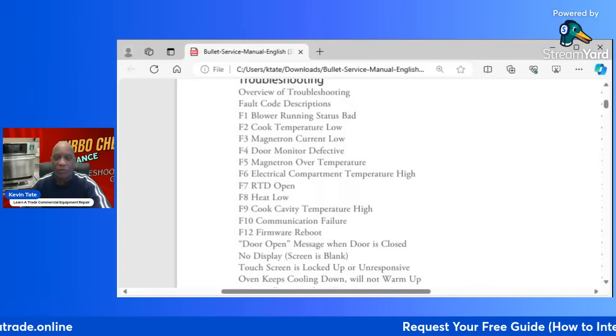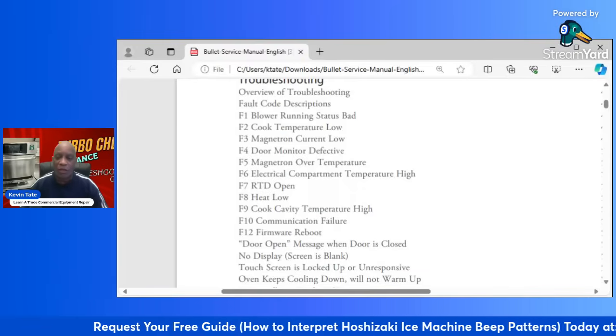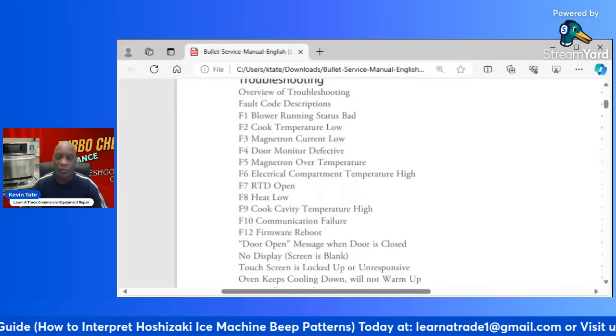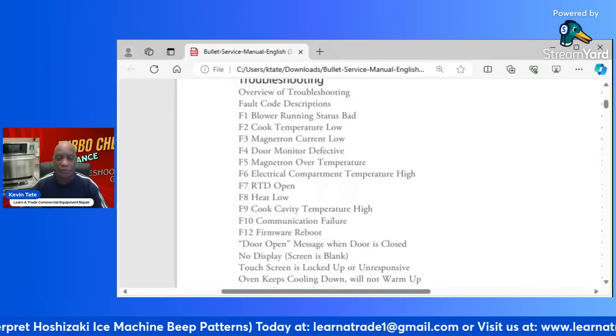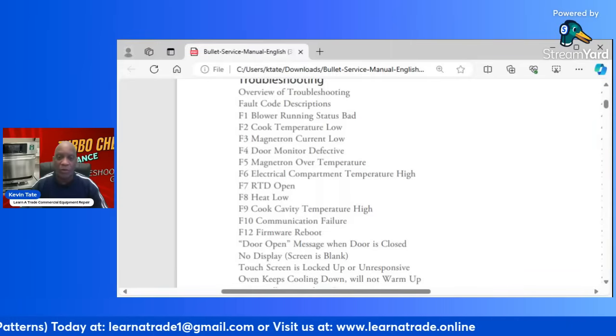And with the high volt circuit, you want to check your number 4 terminal on the high volt transformer. On each high volt transformer, you want to go from ground with your meter on ohms.